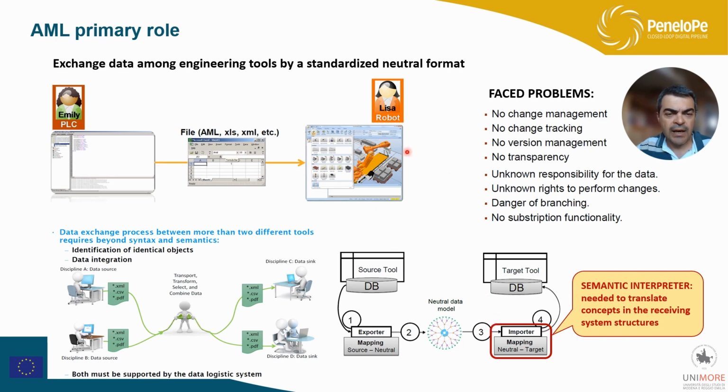So RoboStudio has to accomplish two main steps. The first one is to read the file and to recover and understand the semantics of the signals. So the AutomationML file needs to be read, the signal role class needs to be recovered, understand the type of data, the ranges of the values, and so on. So we need to understand the semantics of the data. And then we have to map these semantics against the RoboStudio data structure. So the second step in reading the file is the feeding of the RoboStudio data structure with the information that has been recovered and semantically understood from the AutomationML.